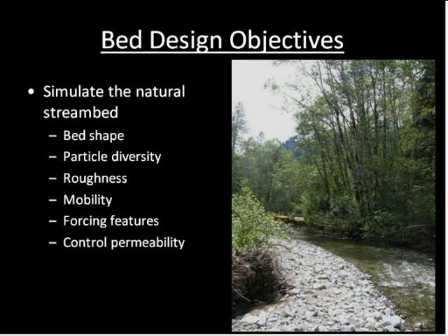Developing a backfill mix that approximates the natural bed material requires a bit of characterization with respect to the stream bed. More data is usually better, but a backfill mixture composed of at least 3 to 4 particle sizes usually provides good bed stability and passage quality.